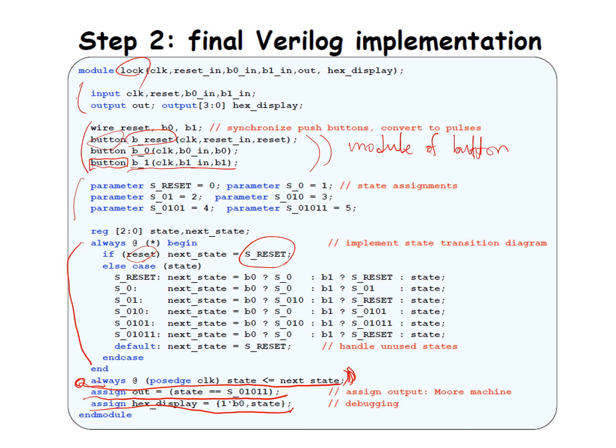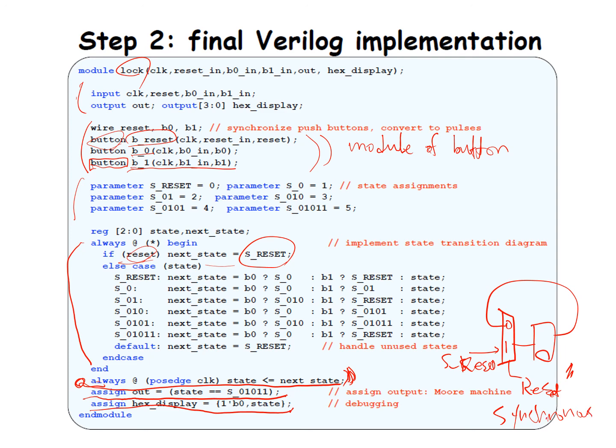For asynchronous reset, the reset happens immediately whenever the reset signal comes in. What about this case? If this is described like that, it is equivalent to a multiplexer, 1 0. So if the reset comes in, it is assigning reset like that. This kind of combinational logic will be a synchronous reset.